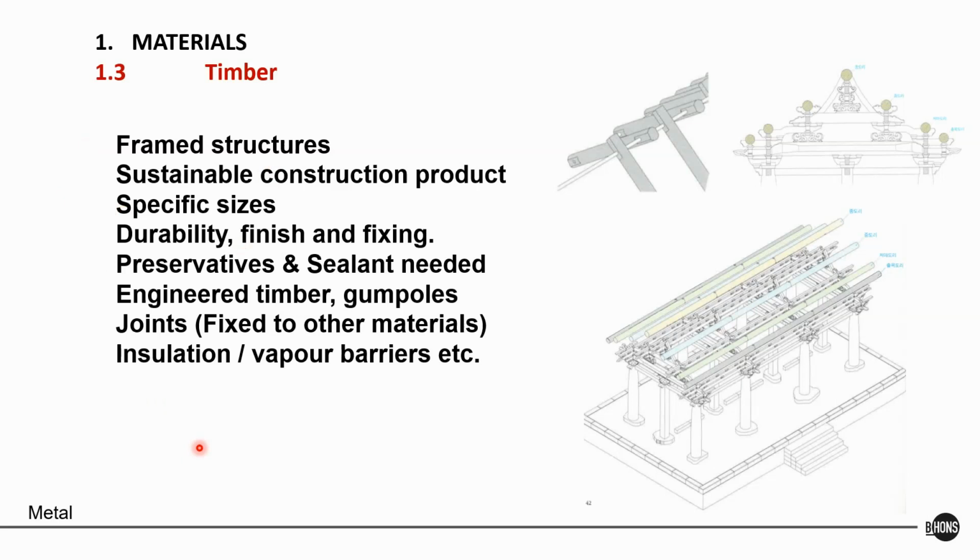So you want, which is good. So if they, they often just get a stamp on that says S5, S7, and S10. If that is certified, you know that you're getting good quality timber. So it's certified wood. Also look at the origin of the timber.